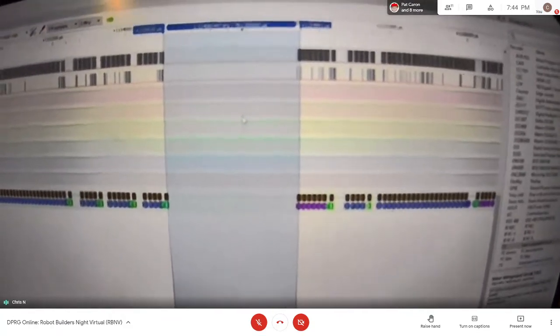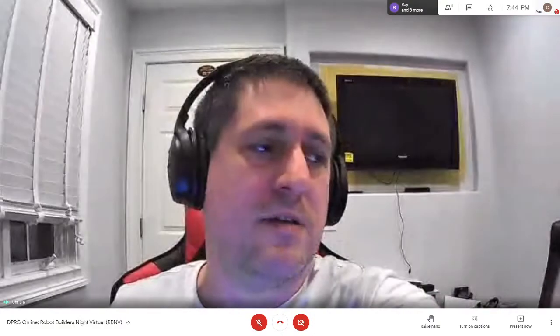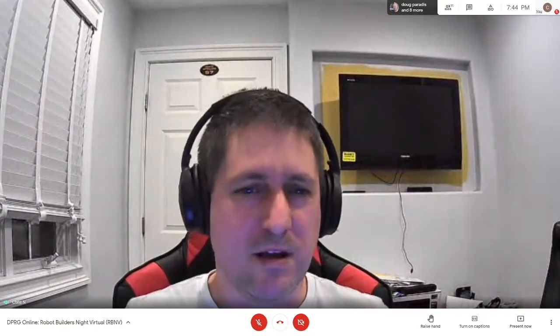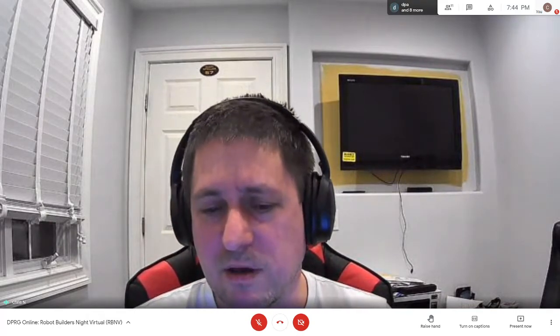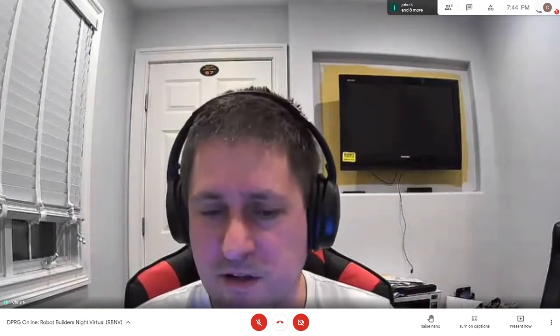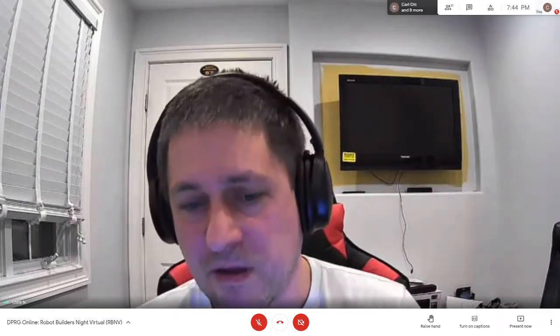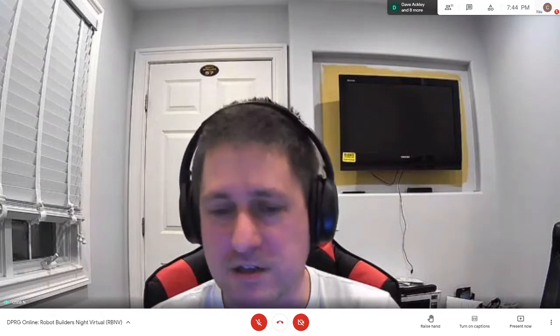And the STM is supposed to deal with that, and it seems like it does. Initially I knew that the BNO is a slow I2C device, and so I thought, okay, maybe the STM isn't configured correctly, maybe clock stretching isn't enabled or something, but I don't think that's the case, because the STM is dealing with it just fine. Like I just said, it sometimes takes 800 microseconds for the BNO to acknowledge the start of an I2C transaction, but all that seems fine.